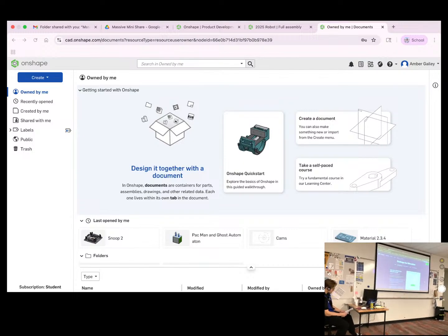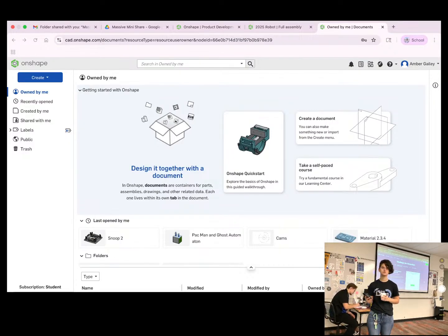We don't want either the FTA, if they're helping you get your robot going so that light's not blinking by your driver's station, or a field reset person redoing the field who comes in contact with your robot, to encounter any sharp edges. So as an inspector, we're going to check around your robot, feel it, any places that look like they could be sharp. We may ask you to take a file to it just to break the sharp edge so nobody gets cut or hurt.